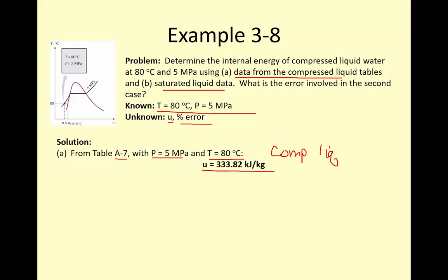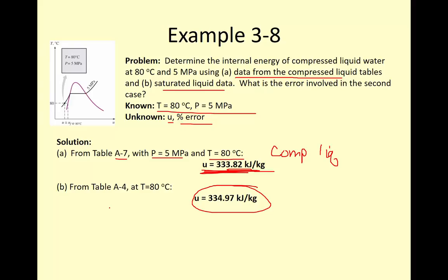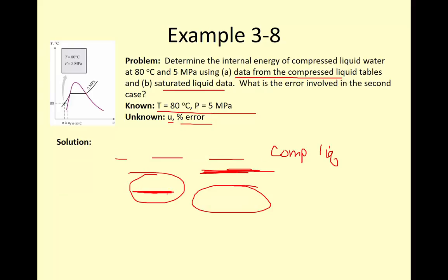So this is the actual value. This is in reality what it is. In part B, we now go and look it up on the saturated liquid table. And it's very important that you look it up at the same temperature. Okay, you don't look it up at the equivalent pressure, the same pressure. You always go to the temperature table and look it up at that same temperature, because if we look back